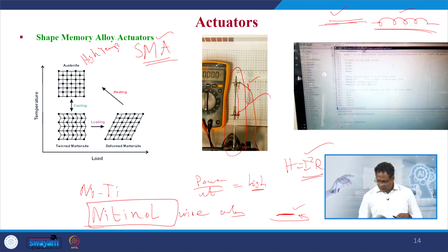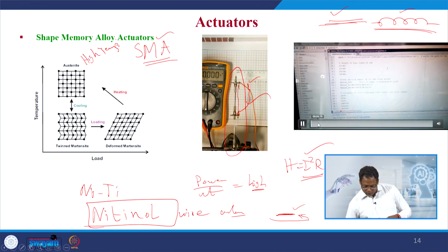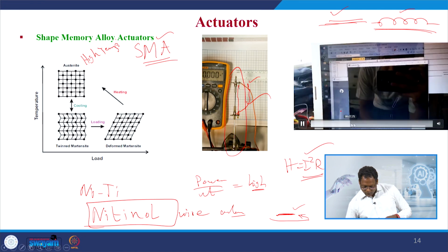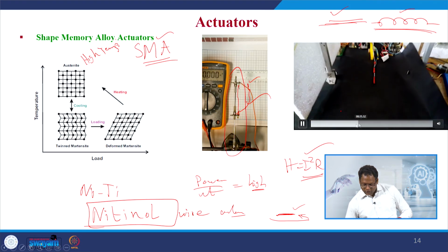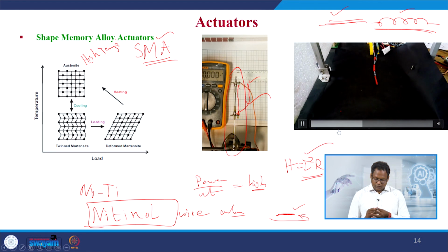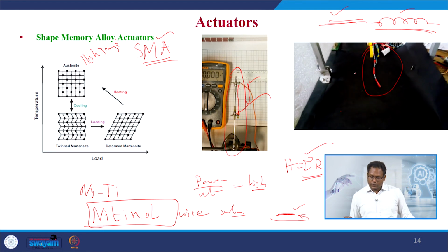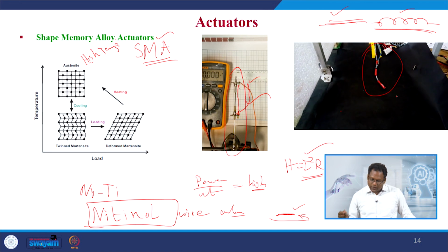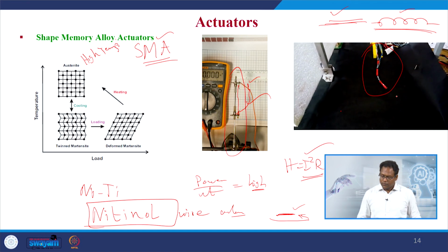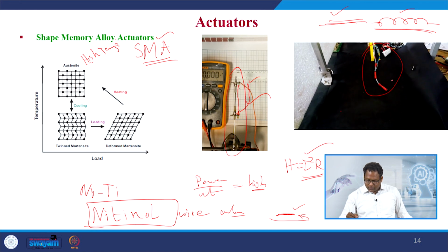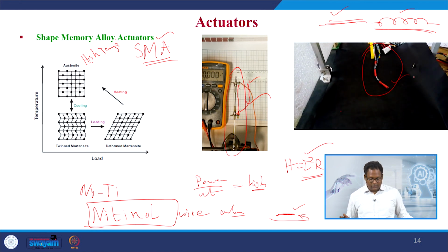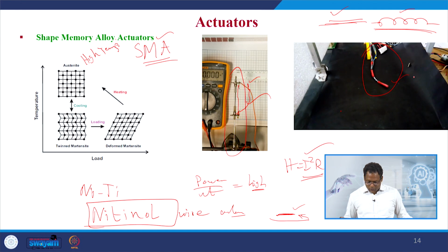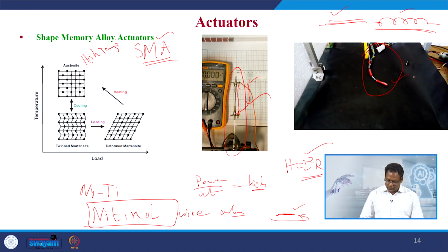And another application is shown here, where we can see maneuvering in the free space. So, this is the needling system we have developed in our laboratory, so that the actuator is attached to the lateral side or surface of this needle, so that we can have this bending of the needle happening, not by a DC motor which is a bulky one, but by a smart actuator, which is the SMA wire actuator attached to the lateral surface.